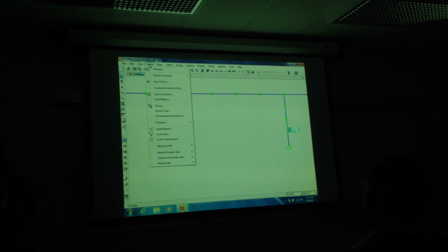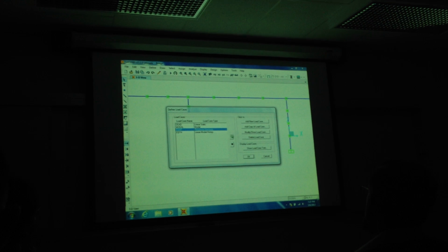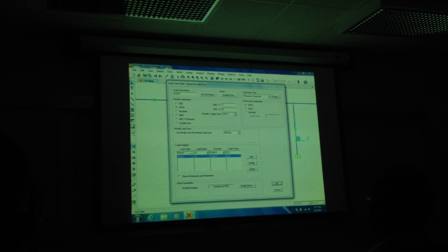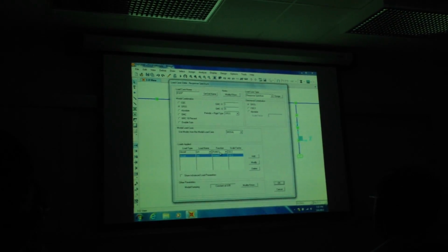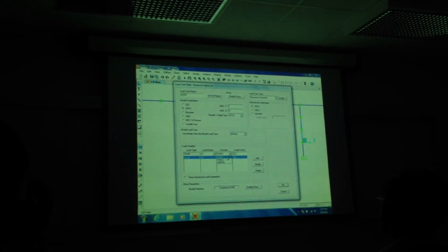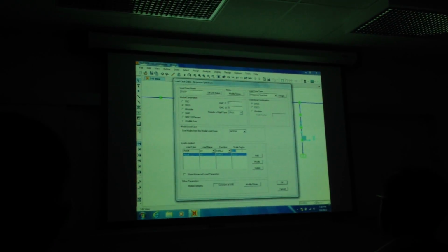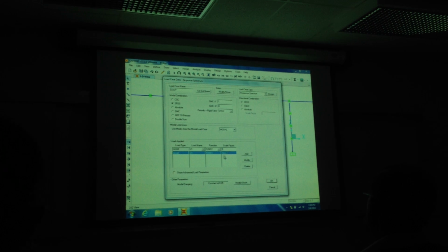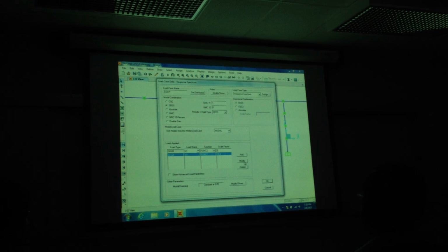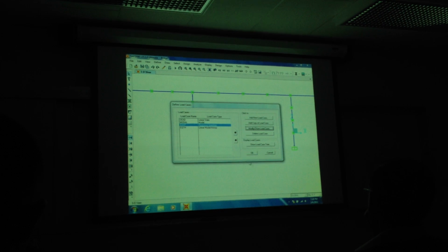Now let's go back to our ARS curve, load case, response spectrum, modify, and before we were using function 1, everything else is the same, acceleration, U1, function 1. This is a response spectrum analysis, not a time history analysis. We're going to switch it to function 2, but then the scale factor should be what? 1. See, it was 32.2 before because we had it in G. This one's in feet per second squared. So you just say modify, and constant damping ratio of 5%, say okay.